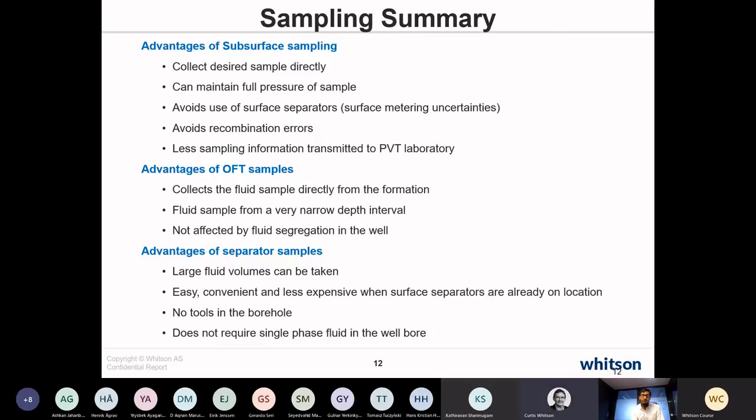And the shrinkage that you're looking for will be measured by the laboratory. But if you have measured the GOR directly at the separator condition in separator barrels, then you don't need the shrinkage, right, Curtis? No, but they may want that. They may be using empirical correlations of that shrinkage, and not just shrinkage from separator conditions to stock tank, but through the actual remaining stages.